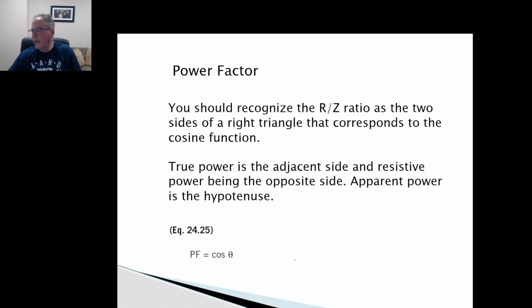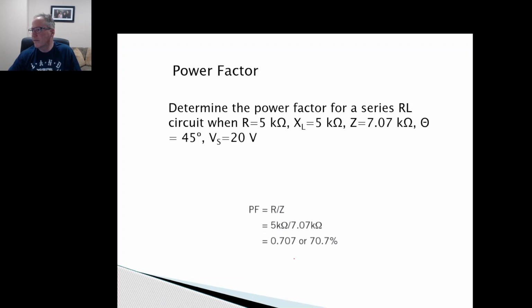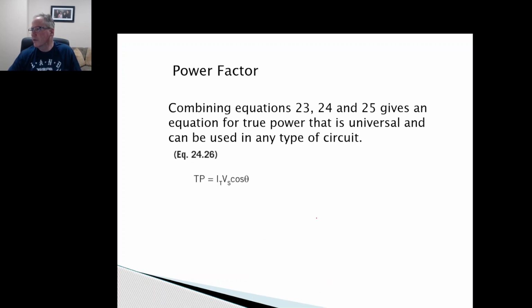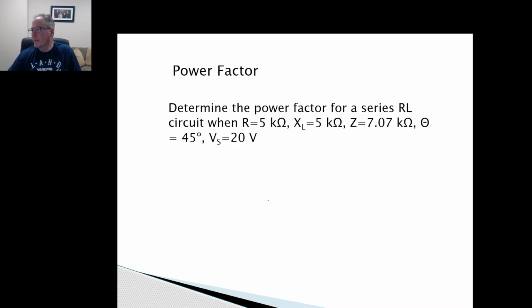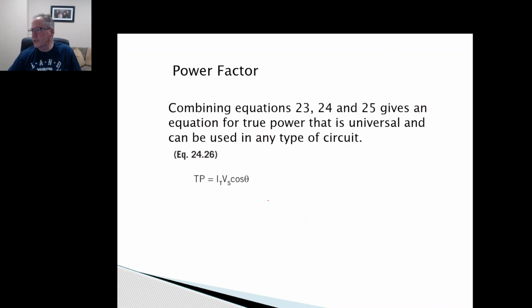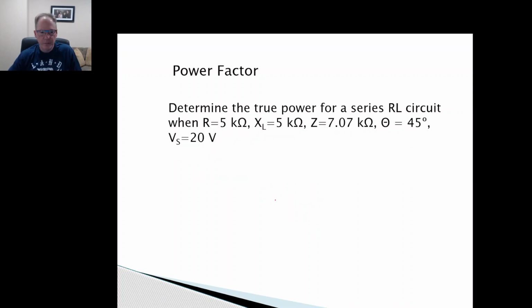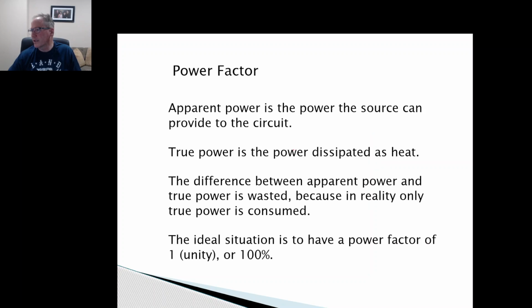All right? So you can look at these and do these calculations. So if we combine some of these formulas to calculate the power factor, we end up solving pretty much all of our equations here. So this is just another way of determining the total power. It's just the I total times the voltage times cosine 45 degrees, right? So we just take the calculations there.